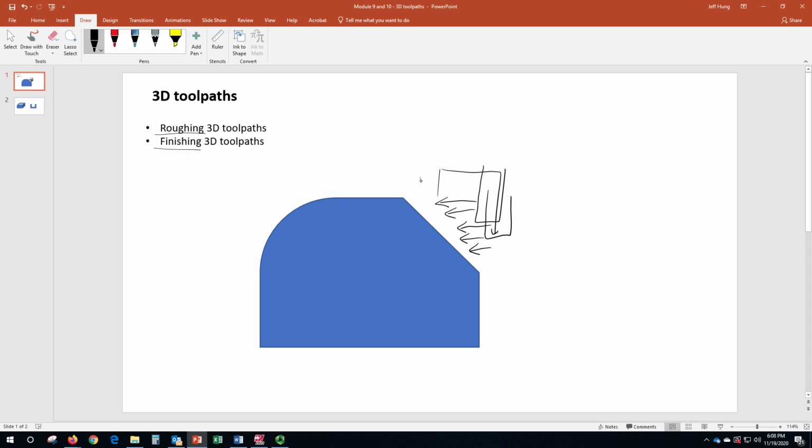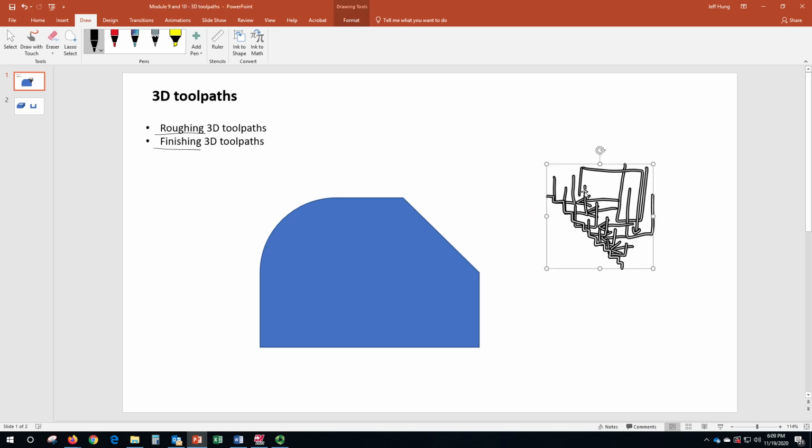So now if I do that, let's say for the first layer, the cutting tool ends here, the second layer, the cutting tool ends here, the third layer, the cutting tool will end here, and so on. So this means I will have this kind of steps at the end. Now, if I have a finish cut, let me finish it. So I will have something like this.